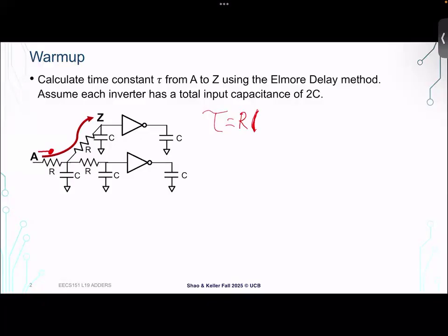I guess 1, 2, and then there's 2 different capacitors from the inverter there. So that's 4, 5, 6, 8, 10, 9 from both paths. Yeah. So, right. So we talked about capacitance as all of the places that current can flow downstream of that node. And I do count 9C on this diagram.